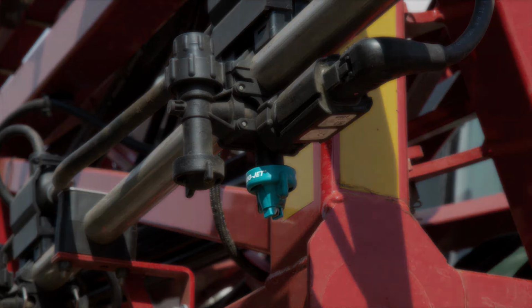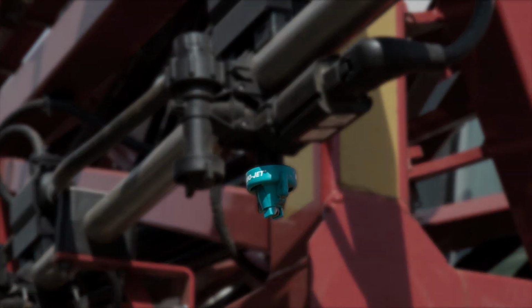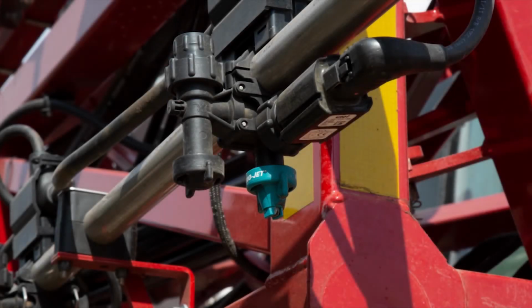One big thing to call out is we're pulsing one nozzle individually on this machine. That one nozzle pulses up to 10 hertz, or up to 10 times per second. When we look at the ExactApply system, we're able to pulse up to 30 times a second, depending on how we have it set up, which is one big advantage when we talk about higher application speeds or higher application rates and speeds. You can get a checkerboard pattern out of your applications when we look at this AIM Command Flex system at higher operating speeds.